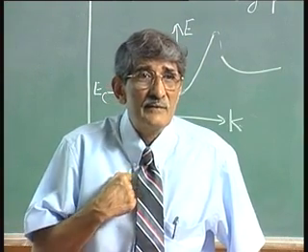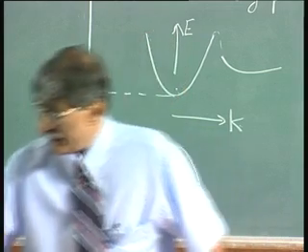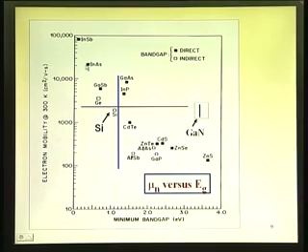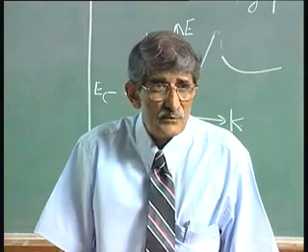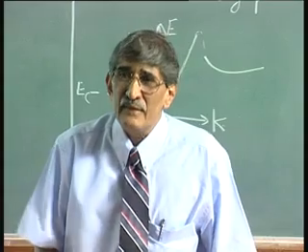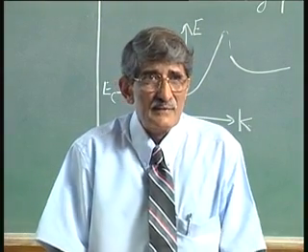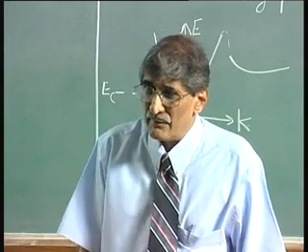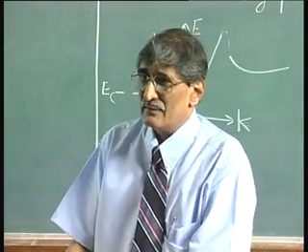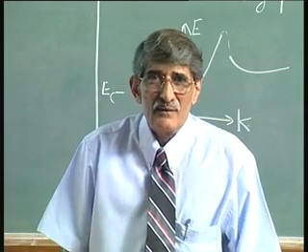Now the point that we are trying to make out was a material like indium arsenide, whose mobility is something like 20,000. You just don't look at it for microelectronics. Reason? Its band gap is some 0.33. So its intrinsic carrier concentration is up about 10 to the power 16 or 10 to the power 17 per centimeter cube. So if you put dopants of the order of 10 to the power 15, what will happen? Intrinsic carrier concentration is 10 to the power 17, dopants are 10 to the power 15, the dopants are buried in or submerged in these electrons which are already present.